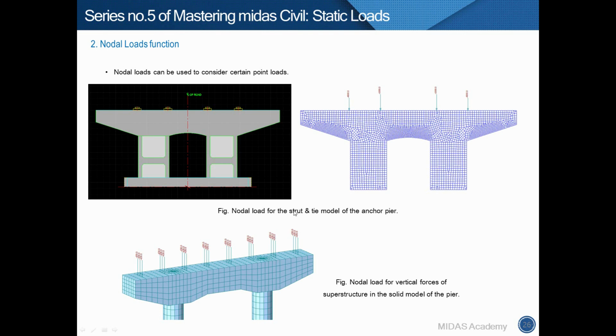And these example models are plate and solid models for a pier. Nodal loads are considered to apply the weight of the support structure to the top of a pier. So you can input the load using the nodal loads to each node directly.